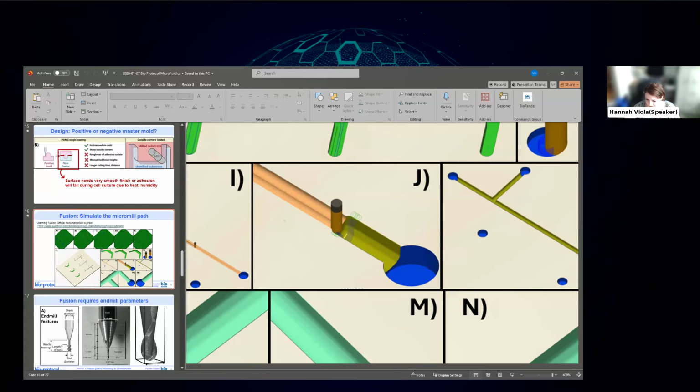What would be the resolution in the Z direction? How would it depend on machine and what machines you recommend? I think the resolution is probably more limited by your tooltip size than by the machine itself, because any micro mill is going to have different XYZ resolutions, but they're around 0.1 microns most of the time, I think. At least ours is. I think the machine cost depends more on how fast your spindle speed can go than the resolution.